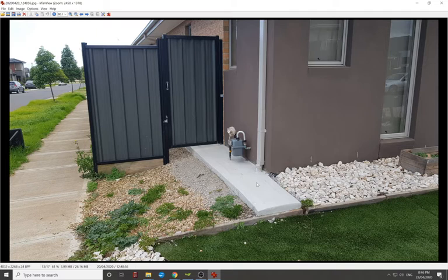I mean, you wouldn't engineer the slab, do soil tests, design a slab for the ground, and then say, well, the whole thing rests on whether you have a concrete apron around the house. It sort of has no logic to it. But it happens a lot. It's a constant thing I'm hearing when I'm going to jobs, that, oh, you've got to get a concrete apron around the house within the first 90 days before the main inspection, or they won't extend our warranty, or that if there's a cracked cornice, they're not going to repair it until you do that. Which I just don't think is true. I just don't see how it's true.